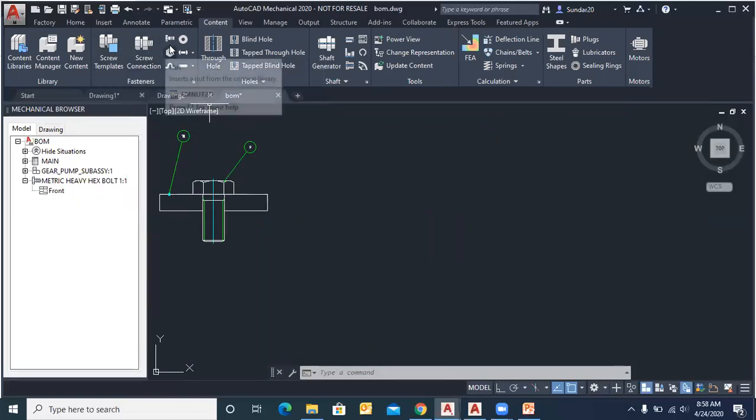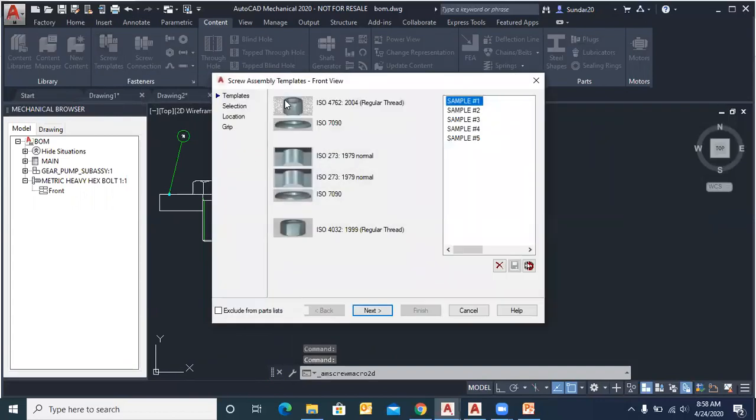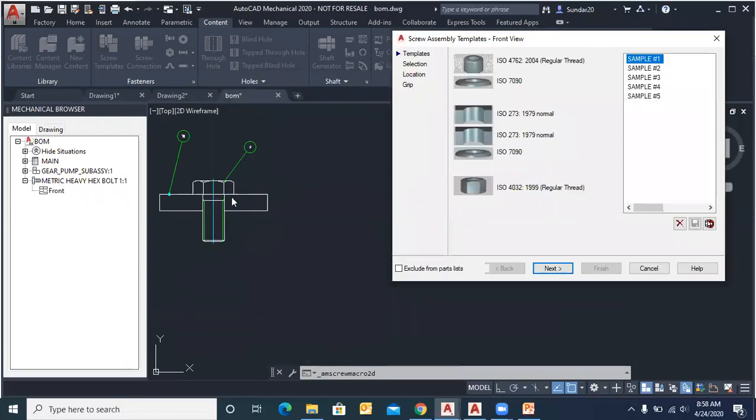So we can see if you take any screw template, it contains a set, where we can also give a bolt connection along with the washer, with the hole and the end washer, and it ends with your nuts. We can directly customize this information, and while we insert this into your AutoCAD Mechanical, everything will be available as a set. Like this we can set screw templates, and directly we can insert them, where much of our time is saved while setting this screw assembly template, where everything is set within a few clicks.